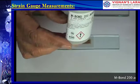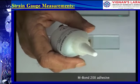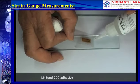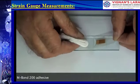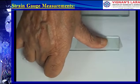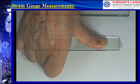Then the tape holding the gauge is held at an obtuse angle to the surface of the part. A drop of M-Bond 200 adhesive is placed at the join of the tape and the part's surface. The tape is then held over the surface at a shallow angle and pressed down with a smooth sliding action using a folded gauze pad, pushing out all excess adhesive all the way to the end of the tape. Thumb pressure is applied over the gauge for at least 1 minute.